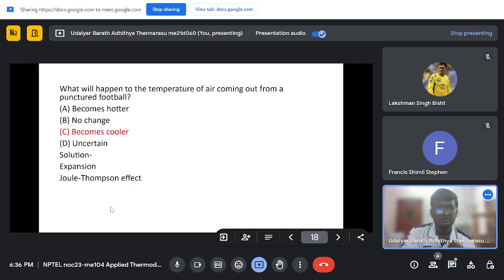In the throttling case, if you pass a liquid, it may come out as a vapor and liquid mixture, because during expansion the density has to go down. The fluid takes its own internal energy to convert phase, since you need latent heat, so it consumes its own internal energy and the temperature of the fluid goes down. That happens in throttling, but not in a nozzle, because there the energy is converted to a change in kinetic energy.